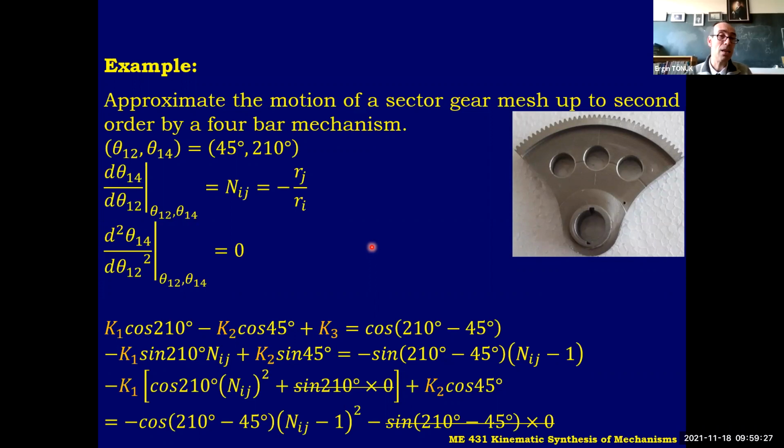And as you see, we have two, if you like, kinematically free parameters. You can change these as you like, and you can change the design. You can have better link lengths, better, I don't know, transmission angles, etc. Okay, but the equation is not linear in terms of these unknowns, so you can't predict what is going to happen.